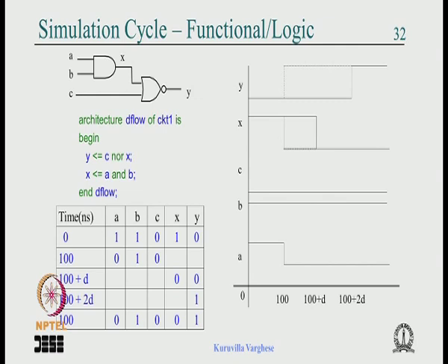Now the delta cycle is not a magic by which you can create different behavior, different circuits and so on. So you don't worry too much about the delta cycle and say this assignment happens after the delta cycle, so what circuit do you get? Nothing. You write the statement, which we are going to see what it means as far as synthesis is concerned. You stick to that rule.